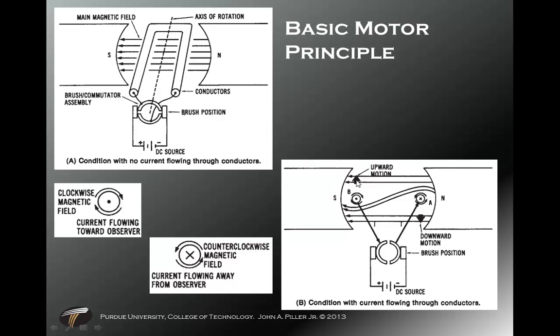Here's a view of the rotor. It is going to spin in this clockwise direction because current is flowing around this way on the B wire and around the other way on the A wire. If you hold your left hand in a curled format, almost a fist but an open fist, your thumb is the direction of the current. Your fingers wrap around the conductor and show you the lines of flux that are going to flow on the conductor that are going to react with the lines of flux of the magnet.